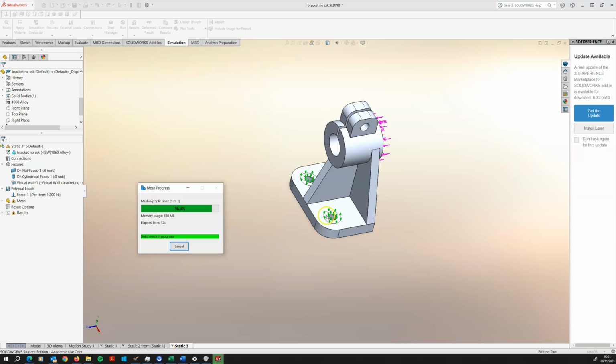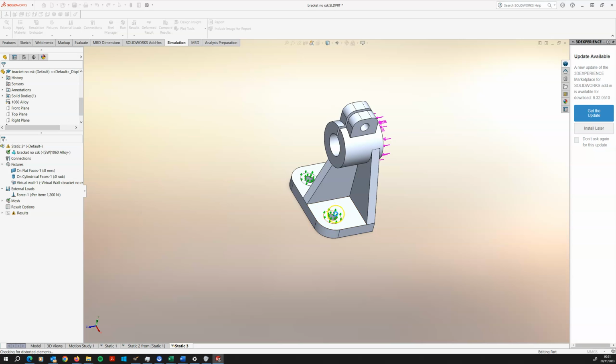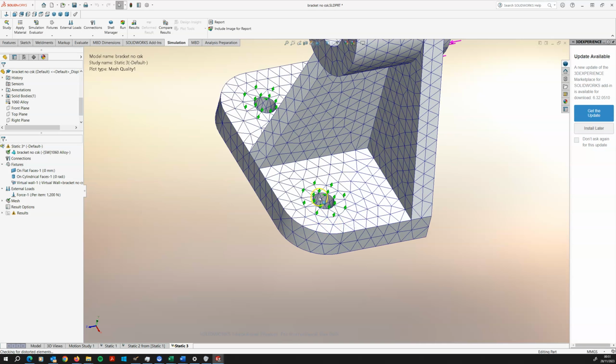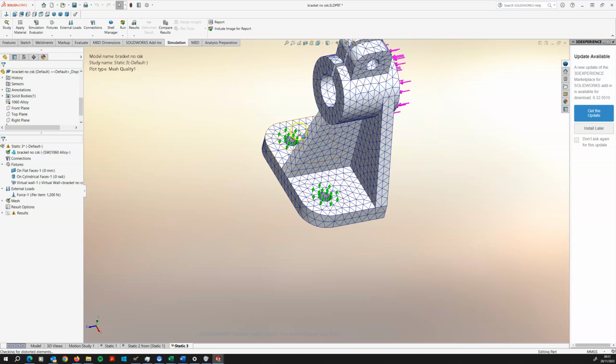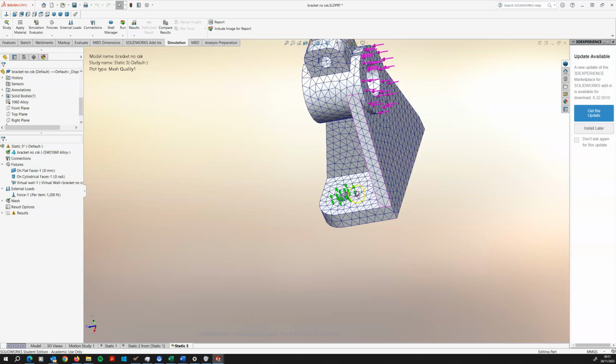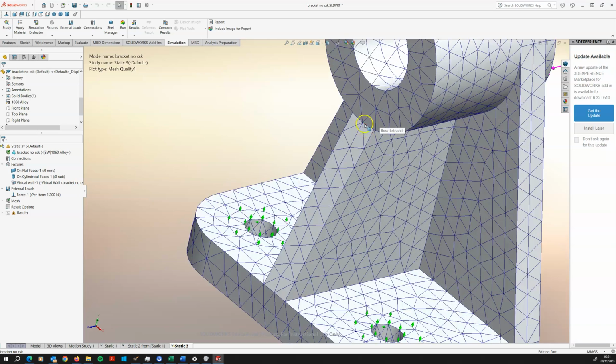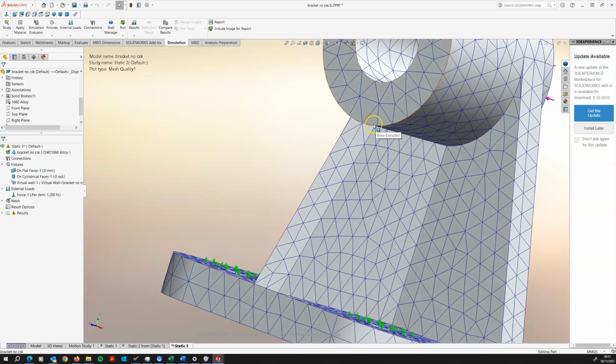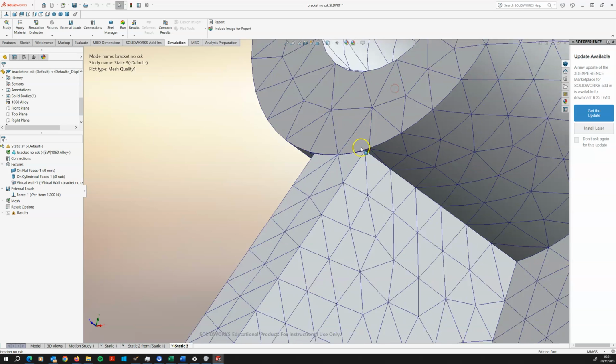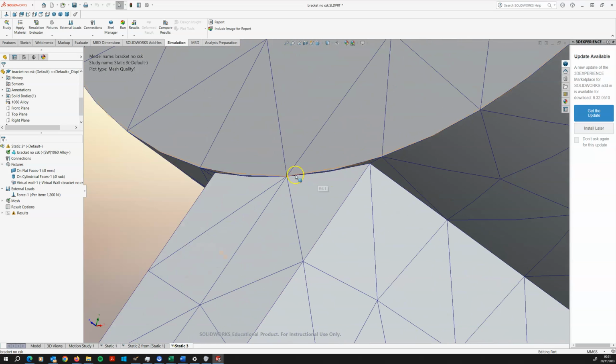but what I'd like to do before running the model though is refine the mesh a little bit. We already know we're going to have fairly high stresses around the bolt holes. We saw that from static 2. And we also know that we're going to have stresses around about where the rib meets this flange down at the bottom here. There's compressive stresses. And we have some tensile stresses at the back here as well. Also, there's a slight issue with the geometry, the way this cylinder meets that rib there. It meets at a very sharp corner.